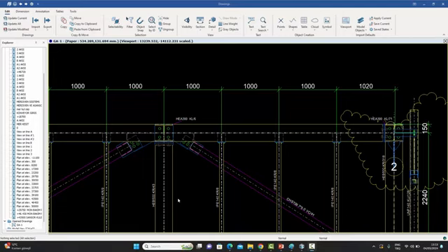The first and the most obvious one is you can directly insert these symbols anywhere you want on your drawings just by clicking on a point, and then that symbol will be inserted at that point. That's the most obvious usage. The second usage is that you can make them part of a text. You can have a text around it. It could be a multi-line text, a single line text. You can put it somewhere in the middle of the text.